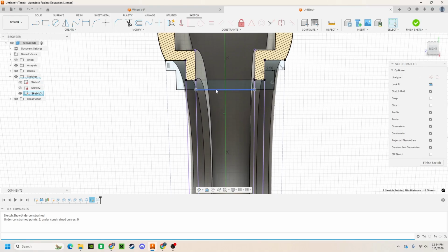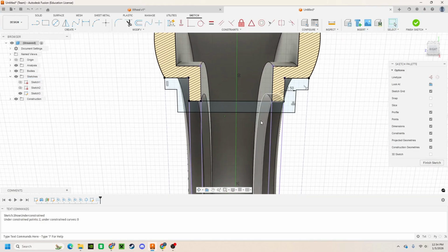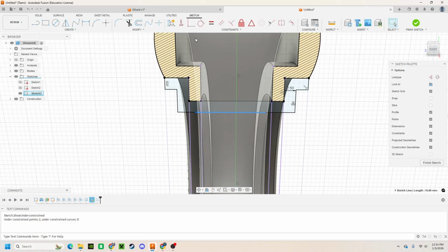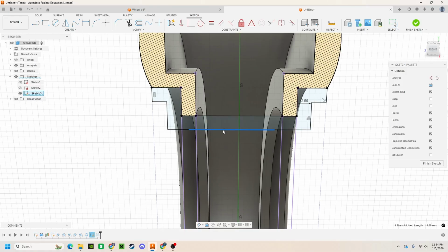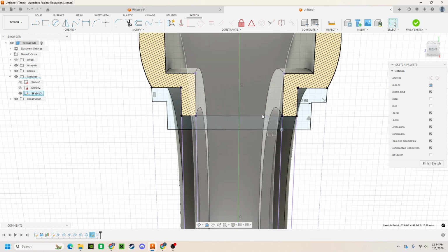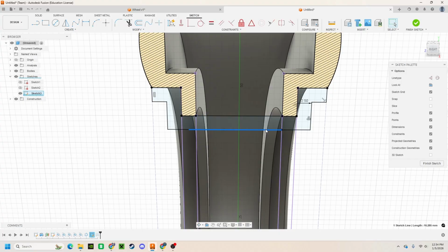So right now, the points that are unconstrained are this line. So when we made that offset, this will come up sometimes. Whenever you offset it, dimensions get deleted for certain lines. So this line, we actually have a line right here that is offset from this line, and it is not constrained. You can see this by it's mostly its distance that's unconstrained.